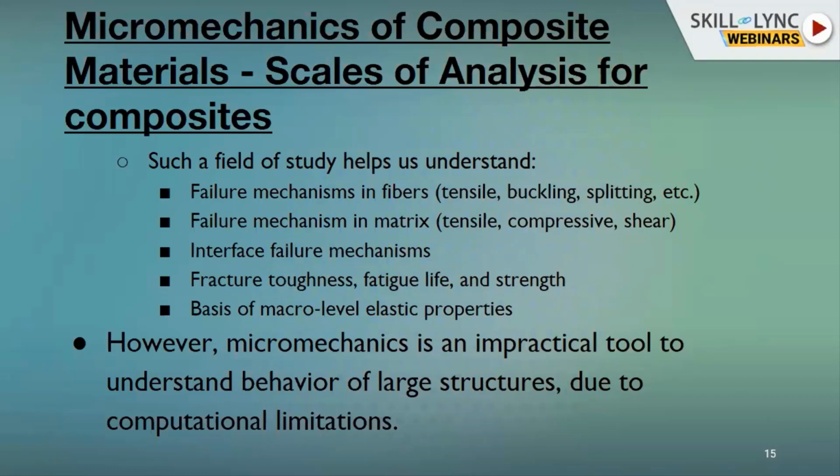Further, the interface between these can also be understood properly by analyzing the micromechanical behavior. With this understanding, the fracture toughness, fatigue life and strength of these composites can be analyzed very easily, and this forms the basis for macro level evaluation of elastic properties. However, micromechanics cannot be used to understand the structural behavior of a very large structure because computationally it will be very inefficient.